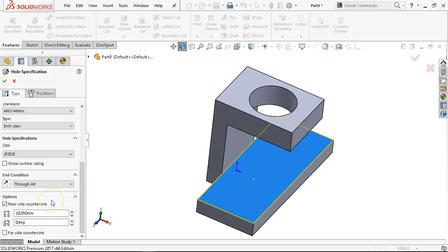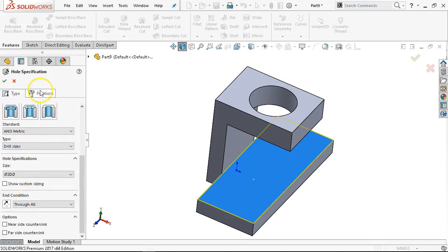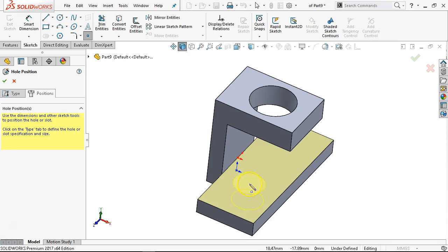One thing of note, if you do include the countersinks. Basically, this is going to be a 0.025 countersink, or edge break on that leading edge. So that 0.05, you split that, and that is what the size of the countersink would be. Problem is that with all this geometry in the way, good luck getting a countersink in there. So might as well just call it an edge break, and we'll be done with it. Oh, there's one more hole on the back side I'm trying to miss.